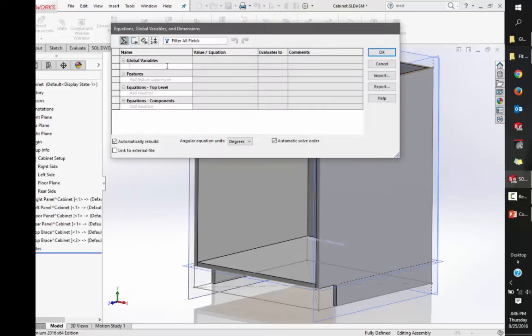It might actually work here. I know if you're in a part, thickness won't work. The reason is that when you create a sheet metal part and you define the thickness of the sheet metal part, that actually becomes an automatic global variable. So if you've ever created a sheet metal part and never noticed it, look over and you'll see that there is an equation folder available automatically. If you click on it, you'll see thickness equals whatever gauge thickness you're using. So assemblies might be different.